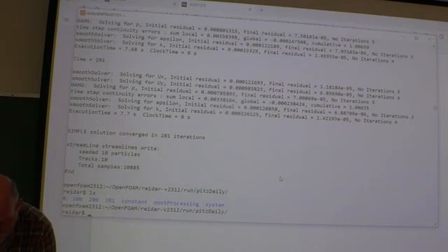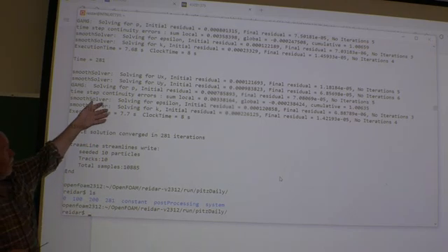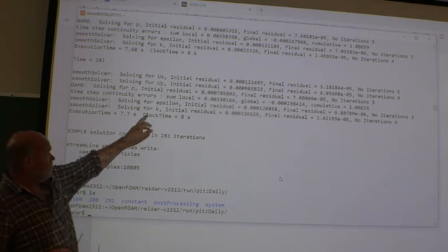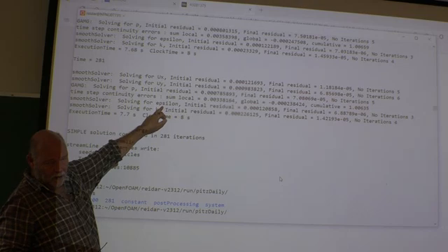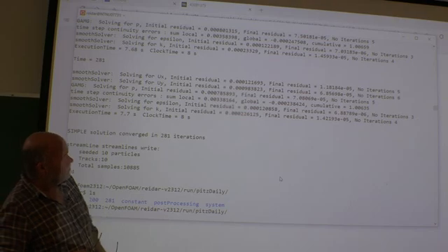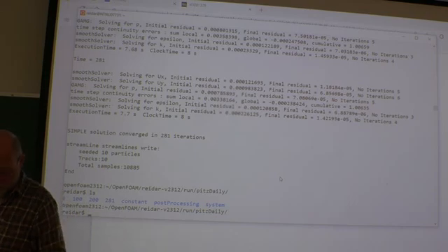Okay, so I've got some result folders, and remember this is a steady state setup. It's only the last one that is of interest. It stops automatically when all the residuals are small enough. And you see it has now solved for k and epsilon. Aha, turbulence, yes. And the overall residual looks nice and small. Shouldn't be any problem here.